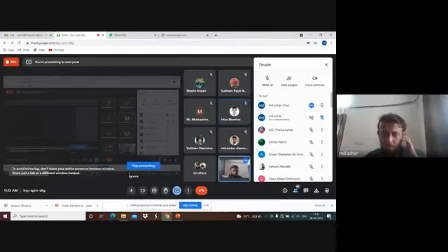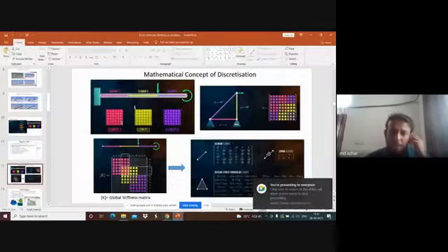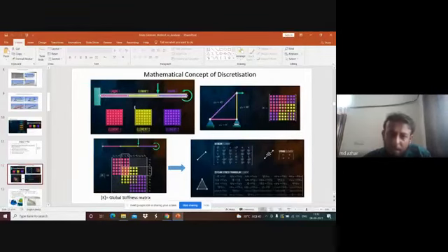Okay. So I was saying that if there's a large chunk of elements, suppose there are 3-4 nodes only, we divide and we want the solution at 1 mm each. We want to see what is happening at the interval of 1 mm, and if the whole thing is just 150 mm long, we'll have 151 nodes.